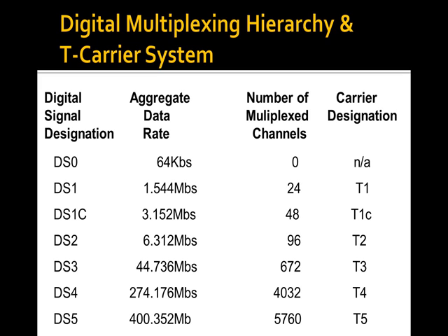To overcome that distance limitation, I need to amplify that analog signal. When I do that, as we looked a few times ago, you amplify not only the original signal, but also all of the noise it picked up along the way. Over several cycles of that, the noise level builds up while the signal stays the same. So you've degraded the signal. That's why I said they were wanting toll quality audio when they looked at their sample rates. Okay, so all of this ties back to that.